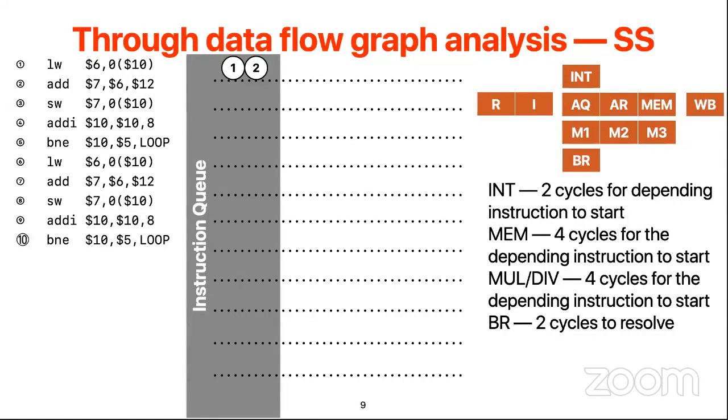Like in the first cycle, we got 1 and 2 renamed. If you look at the data dependency of 1 and 2, yes, there is a data dependency. In the next cycle, we get them into our instruction queue. You look at the data dependency, and you will figure out that 3 is still depending on 2. However, 4 you are now making execute earlier.